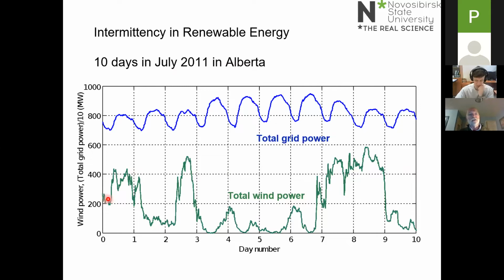Now, the next thing to note from this data is that the wind power indeed is intermittent. The wind power is produced when the wind blows, not necessarily when you want it. So, for example, on day 2, we're getting a lot of wind power at the points where the maximum system demand is. But if we go over to day 3, we get the reverse. There's no strong correlation between the time of day and the wind power production. So the wind power production is intermittent.